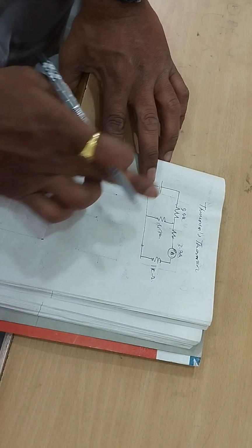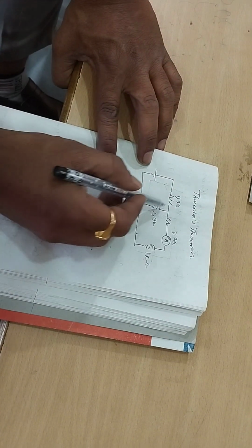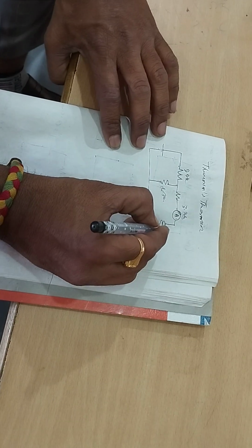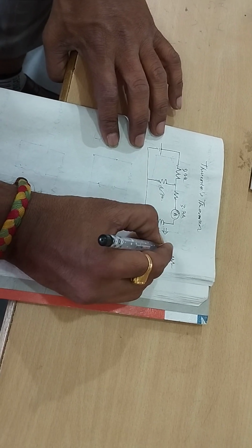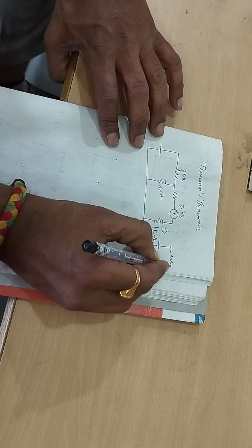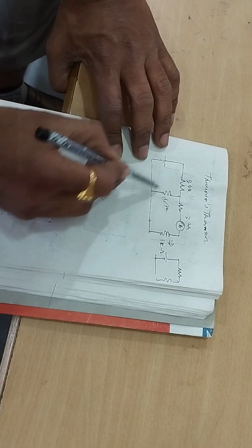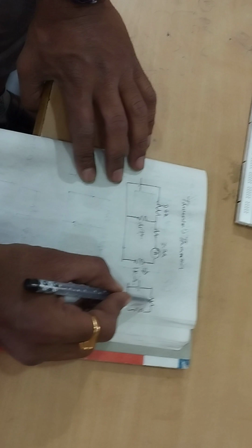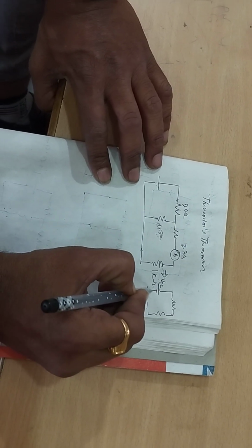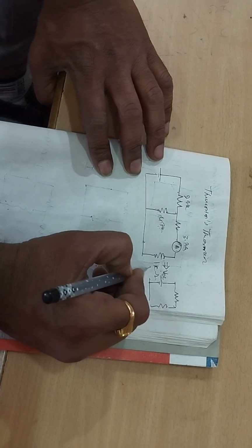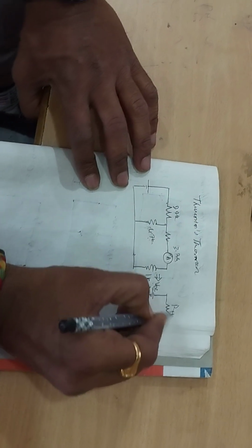Thevenin's theorem states that any linear bilateral network comprising more number of sources and more number of elements can be successfully replaced with a single element in series with a voltage source. Instead of using n number of elements, we can replace them with a single element, and the voltage applied here is equal to the open circuit voltage measured. This voltage can be called V Thevenin's, with R Thevenin's.